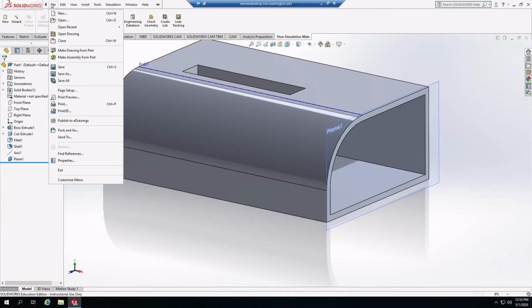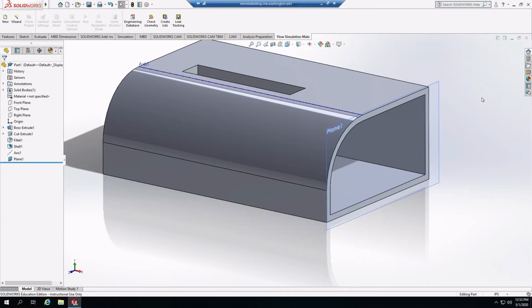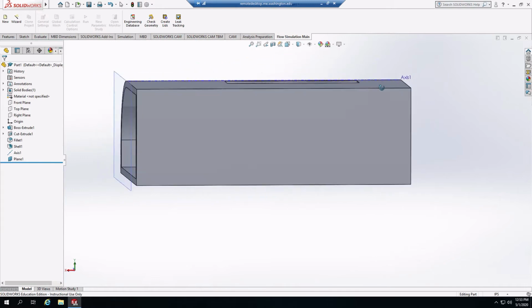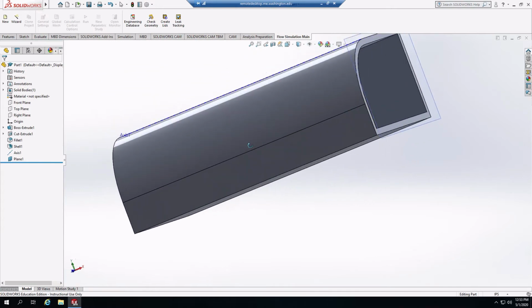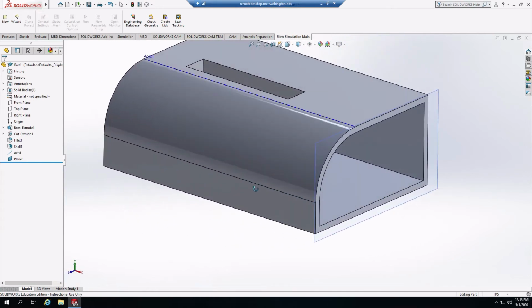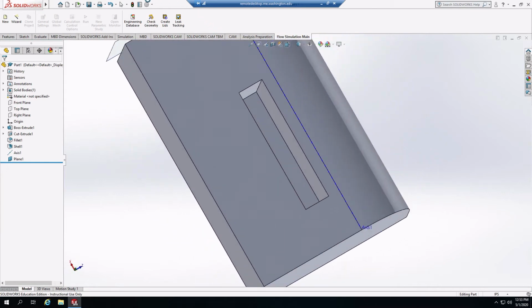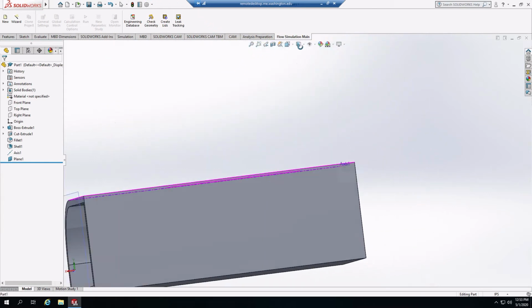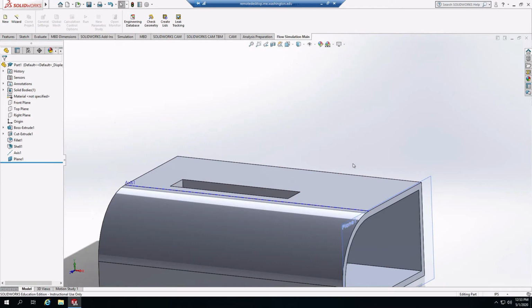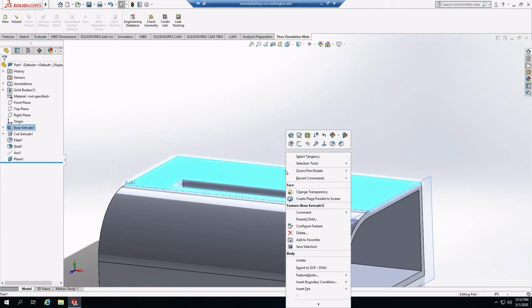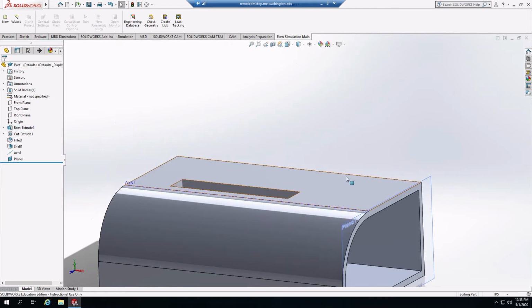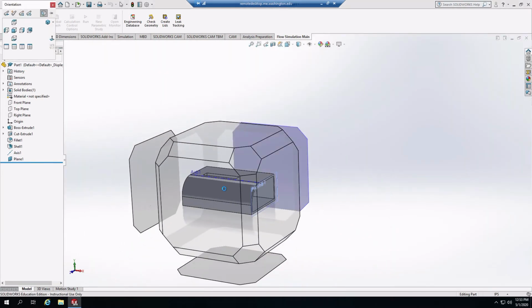We can rotate the model by pushing down on a scroll wheel if you have an exterior mouse. You can also hold left click and drag and select. You can right click on faces, lines, etc. to see properties. You can hit the space bar and it zooms out into this, where you can select different views.